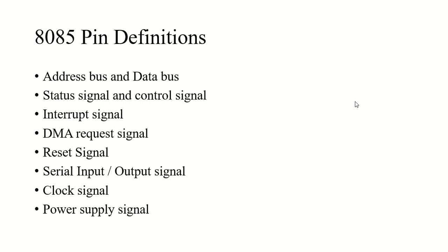It indicates when the microprocessor is performing memory related operations. Then we have the status signals. Status signals are output signals used to give information of the operation performed by the microprocessor. We use S0 and S1 notation, which is line specific for different conditions of the 8085 machine cycle. It can be 00, 01, 10 and 11. 11 stands for opcode fetch or instruction read from memory. 01 stands for read only. 10 stands for write only, and 00 stands for halt.